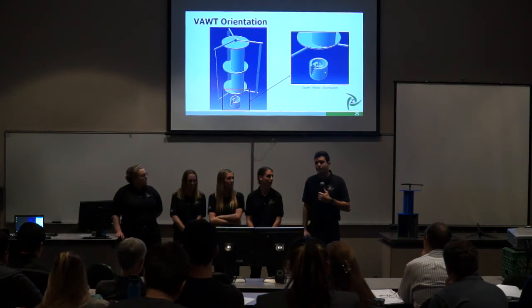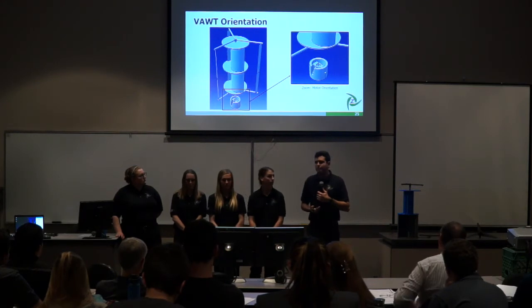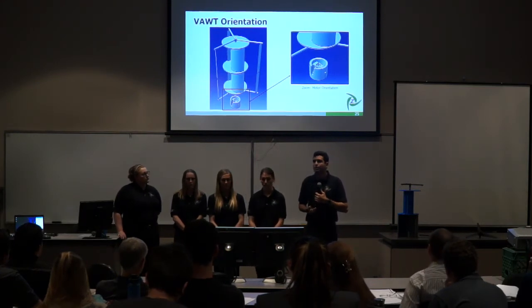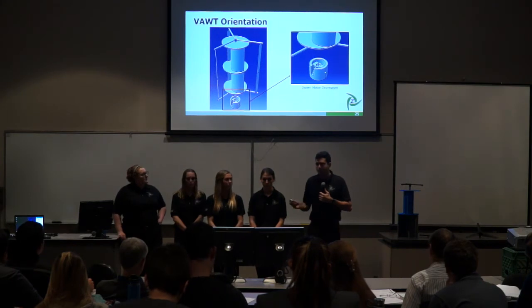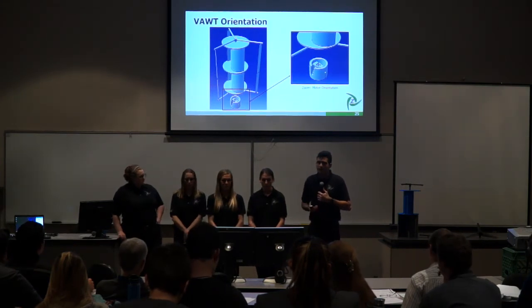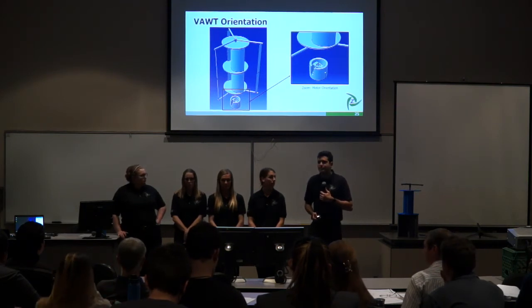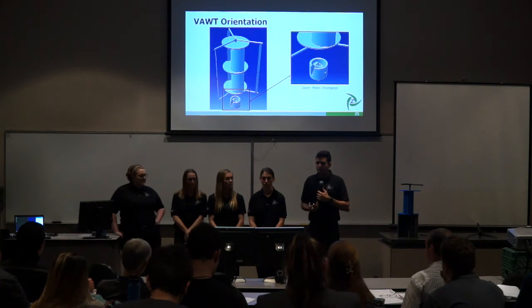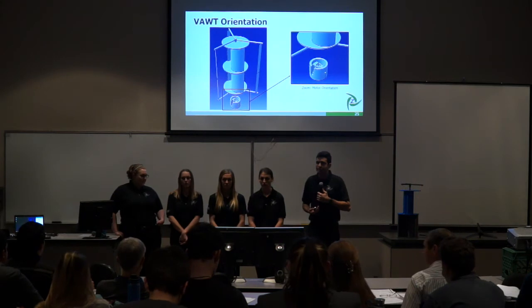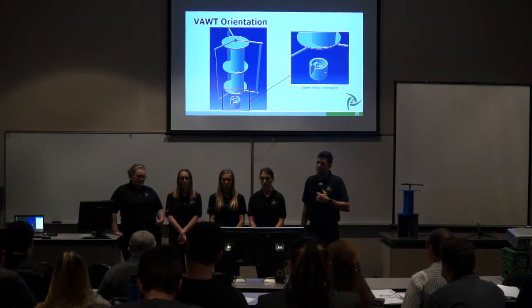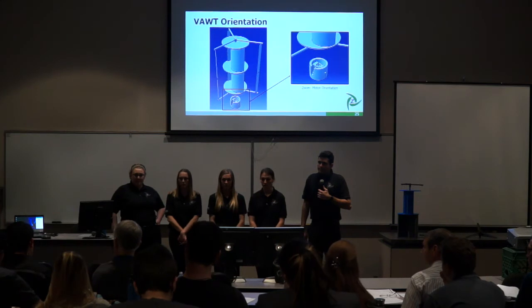Actually, in CATIA, I did find, by changing the density of the ABS to around 75% of the density that's programmed into CATIA, to simulate the infill density of 3D printing with a rough estimate of varying between 50 and 100% for our infills, the entire assembly was 15.15 pounds. Our requirement is 15 pounds for the entire thing. So we were going to change the infill densities and possibly sizing to meet that 15-pound requirement.